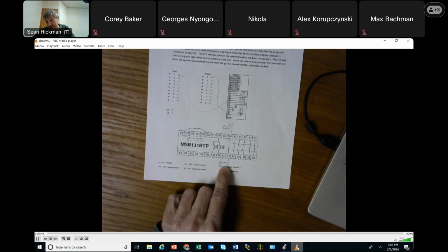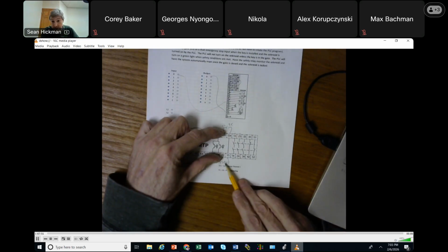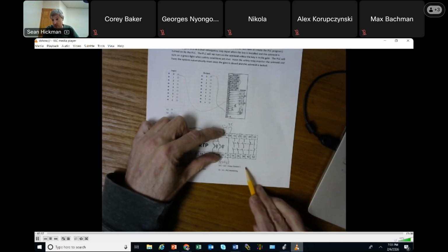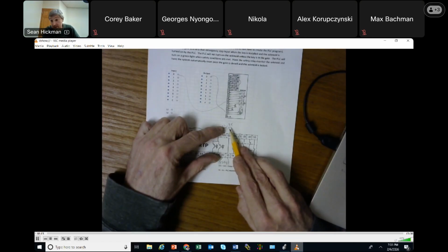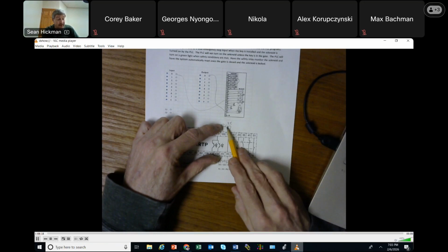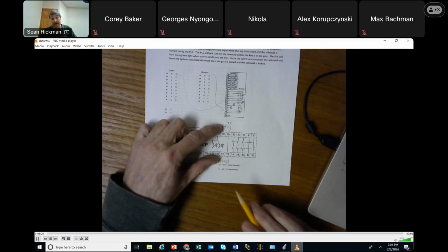A lot of times it's a safety contactor, and then the reset. So these two functions here, you're monitoring your devices, and this could be a big series thing too. This could be a bunch of closed contacts in series. So you've got a bunch of gates and motors and starters and everything coming back to here. In this reset, a lot of times it's a push button, but you could have shutting the gate, resetting it, or resetting something resets it. So these two sets of contacts, how are you feeling about resetting it and monitoring it? Very similar, kind of, aren't they? But they're different. One's open closing, and the other one is looking for it to be closed, but they're almost the same thing.